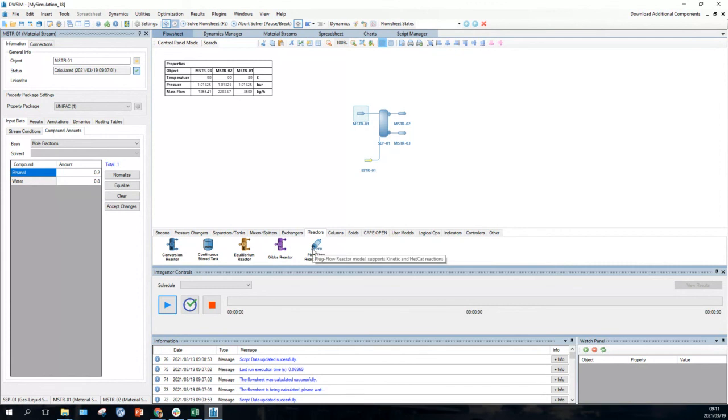And then plug flow reactor, there you've got to put in the kinetics, and usually kinetics for a catalytic reaction, which is what you normally have, they are fairly unique. You're not going to have that model in this reactor. So it is not that often used, but I do believe it's easier in DWSim to put in your own unit operations than it is in Aspen. So you may be able to put in whatever kinetic model you'd like in this thing.